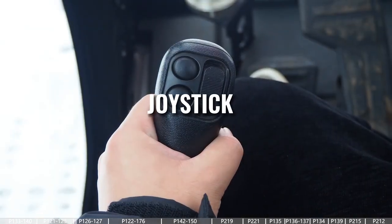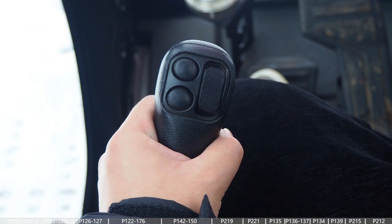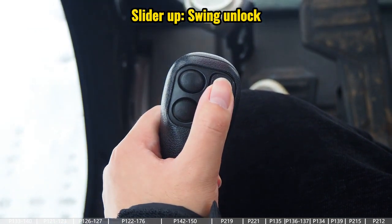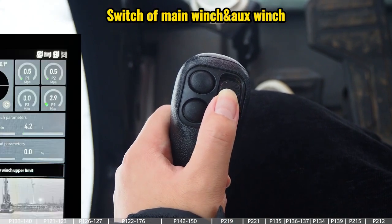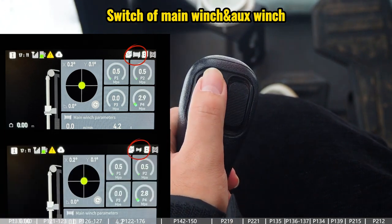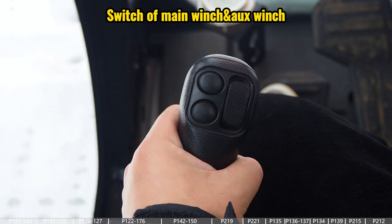In this video, we're going to introduce the functions of the joysticks. Firstly, let's introduce the buttons on the joysticks. For the left joystick, pushing the slider up is for the swing unlock. Pushing the slider down is for one kind of soil shaking auto function. And this button is for switching between the main winch and the auxiliary winch. And we can get the status on the top bar of the display.